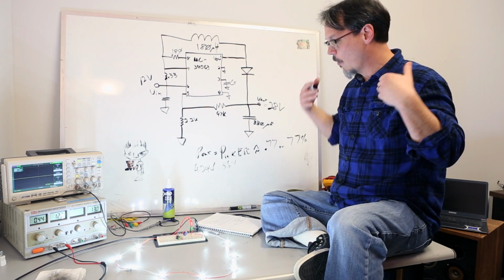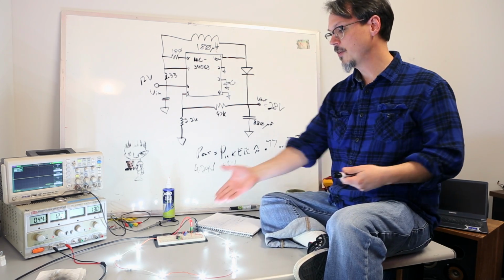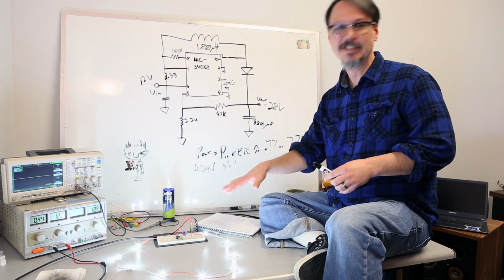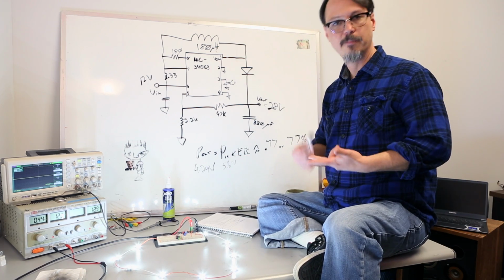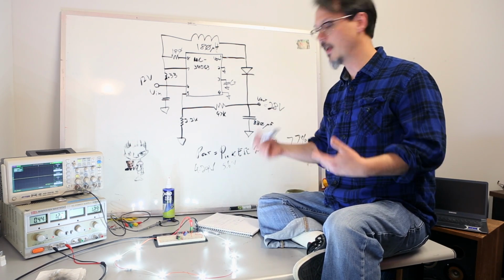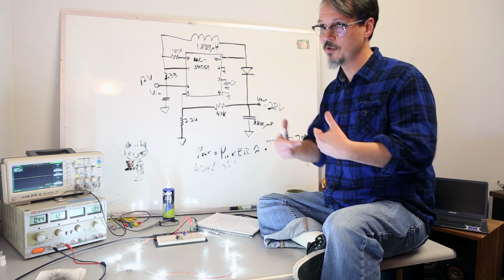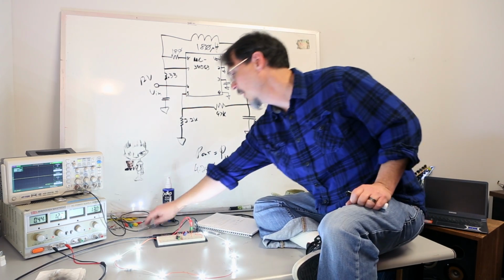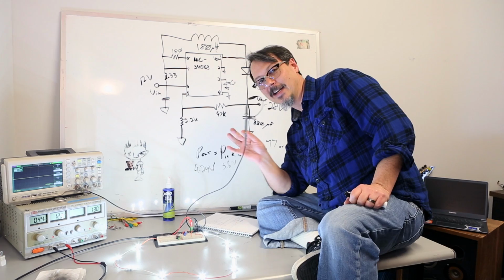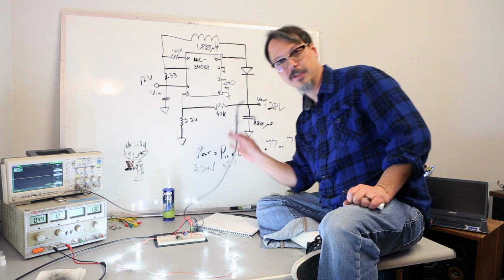But why is it different? Well, as you can see from my circuit, this is not optimized. When you lay out a buck or a boost regulator, switching noise is a thing. Relative positions of the components become a thing. RF becomes a huge thing. Check out my handy dandy poor man's RF loop just to see.